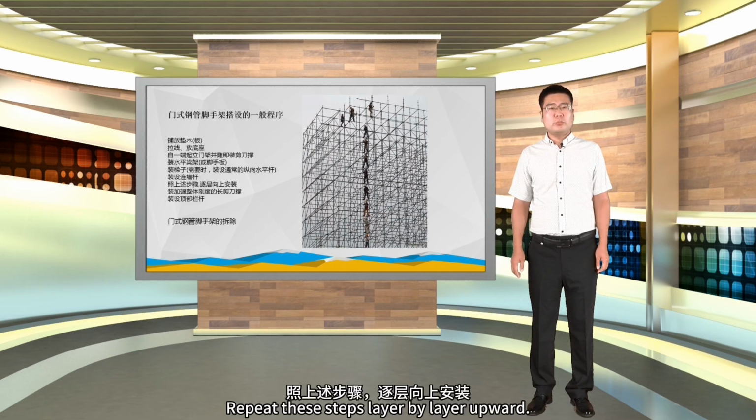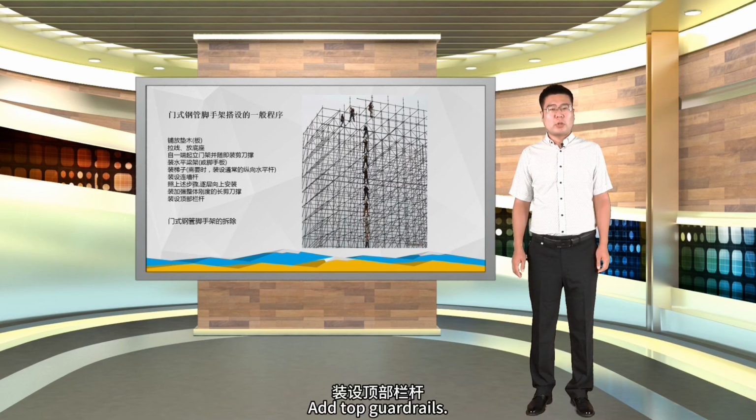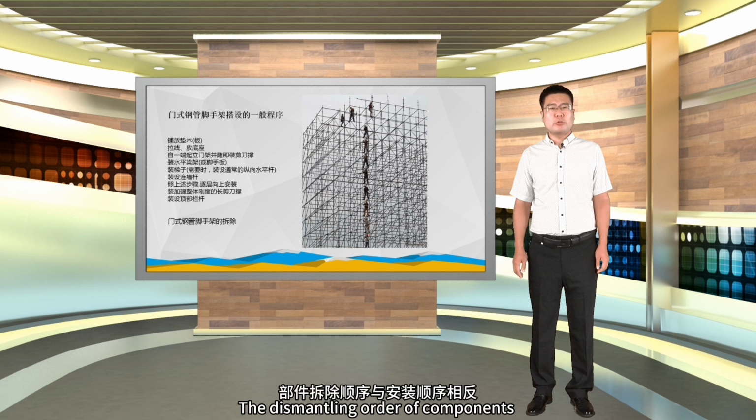Repeat these steps layer by layer upward. Then install long cross braces to enhance overall rigidity. Add top guardrails. When dismantling frame scaffolding, work from the top down. The dismantling order of components is opposite to the installation order.